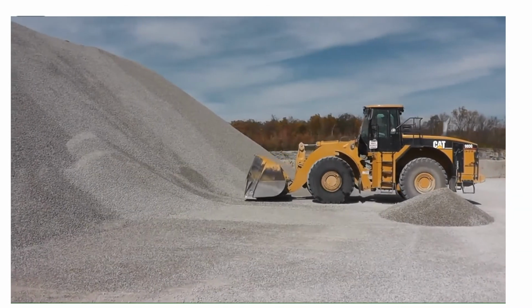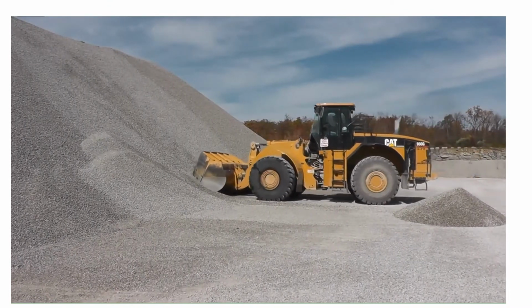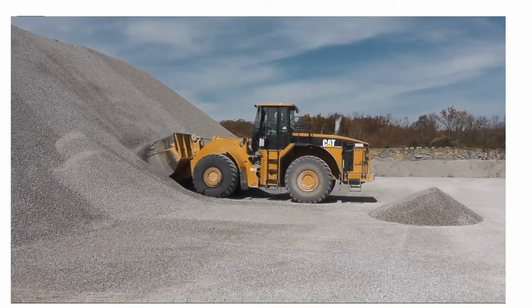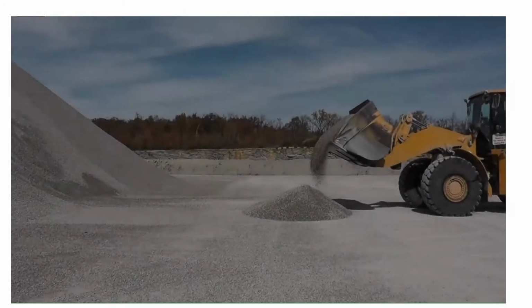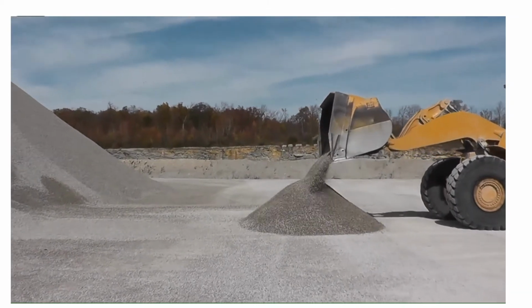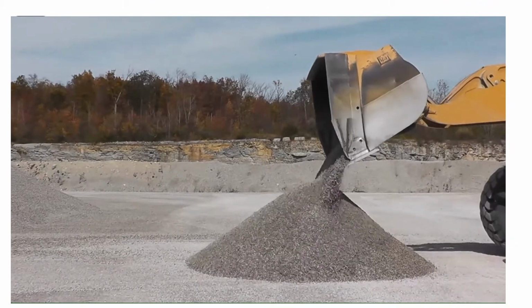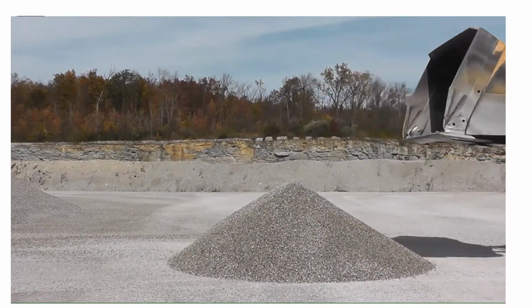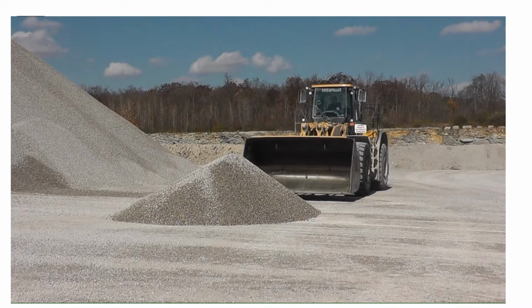This will take more than one pass if the loader bucket capacity is less than 10 tons. Each subsequent pass shall be conducted in the same manner as the first pass, and the material will be uniformly placed over the material from the previous pass. The loader operator should also make sure to leave enough room between the sample pile and any other obstructions so that the sample pile can be mixed from all sides. Once the loader operator has laid out enough material, the next step is to thoroughly mix the sample pile. At this point, the sample pile will typically have an oblong shape.